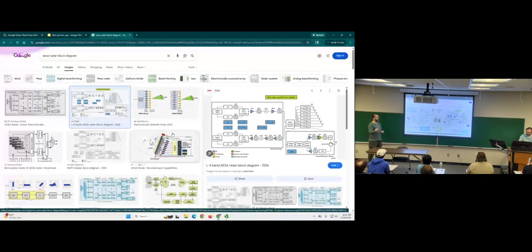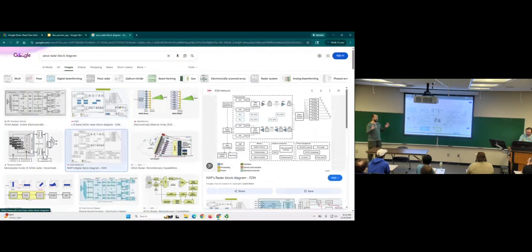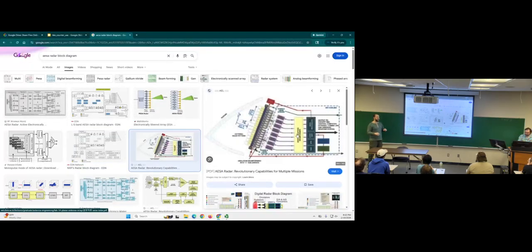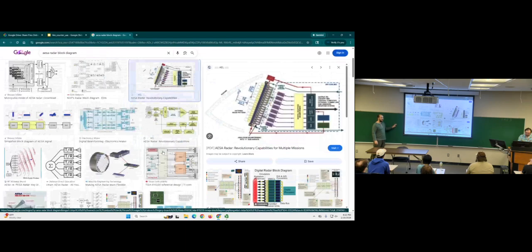Now, you don't actually need to have a full radio per antenna. That's only if you're trying to do a full, military-grade, actively electronically scanned array. Instead, you can feed the same signal to all the antennas and then just control phase and amplitude shifters on each line. A lot cheaper. We're talking on the order of going from $20 million to $200,000. Because instead of 4,000 radios, you only need one. So it scales it down.